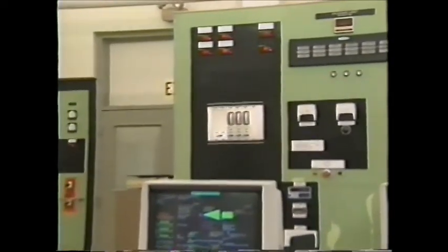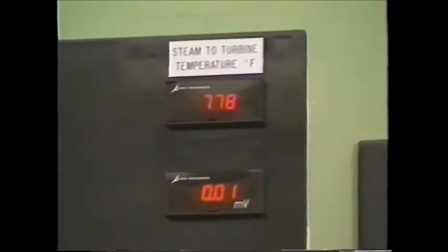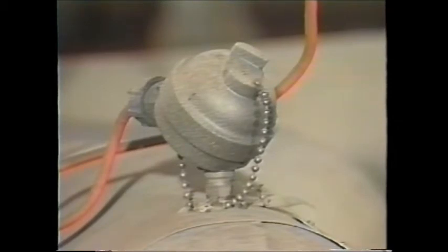In order to have accurate remote indication of temperature, a detector that converts temperature to an equivalent electrical signal may be needed. One type of electrical temperature sensor is a thermocouple. Thermocouples convert temperature to an equivalent millivolt signal, which changes in response to temperature changes. Thermocouples are constructed of two wires made of two different metals. If two dissimilar homogeneous metal wires are joined at each end to form two junctions, and a temperature gradient exists between the junctions, a millivoltage is produced.